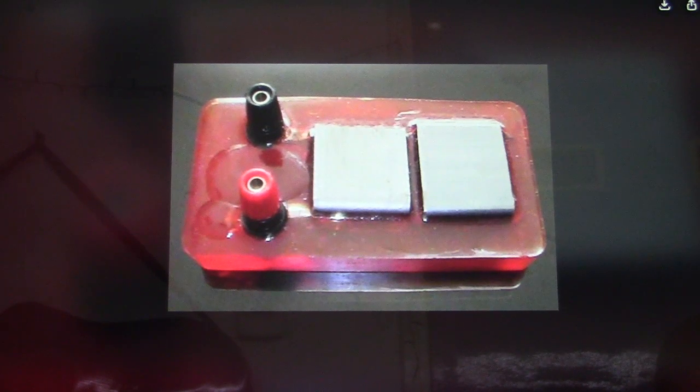Procedure for use. Clean the 2 base electrodes and place them on the ground near the pipeline. Clean the top anode and connect the meter. Place an electrolyte sample between the top electrodes. Observe and record the current's direction and strength. This can be done on a data logger automatically.